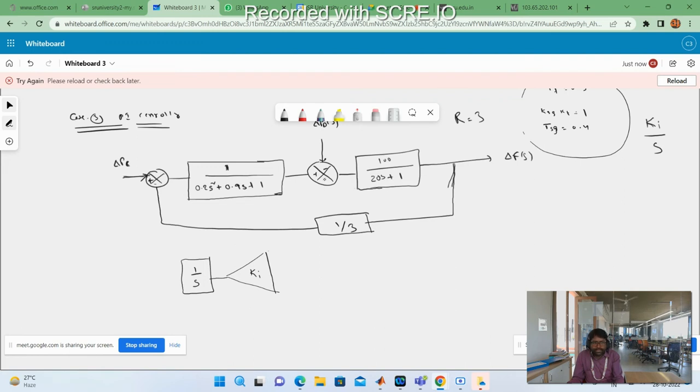And it takes the frequency deviation and sends the signal to your speed changer, and the speed changer will be adjusted, either increasing or decreasing. This adjustment will be done until your frequency deviation equal to 0. If the frequency deviation equals 0, no input goes to the speed changer, and it will not change. Your speed changer position will be changed until you have the delta PC value if there is a frequency deviation. And here we are considering the Ki value equal to 0.09. Okay. Now this is the PI controller, but there is no time today. In tomorrow's class, I am going to explain why.